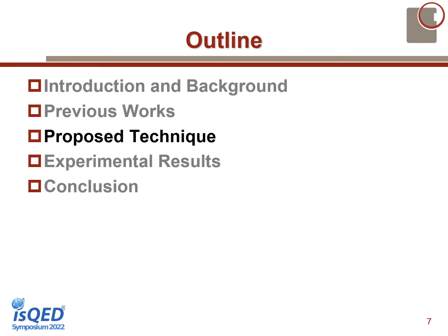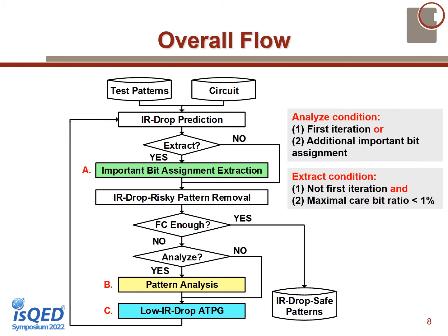Next, I will introduce the proposed techniques. This is the overall flow of our work. We will call it the regeneration loop later on. The input data include the test circuit and its test patterns generated by Synopsys TetraMax. The output is IR drop safe test patterns.